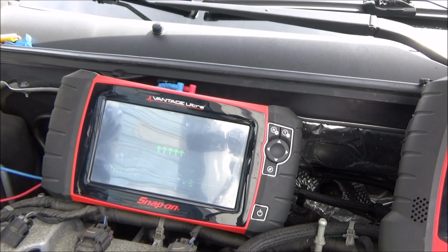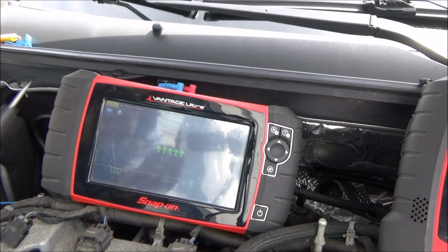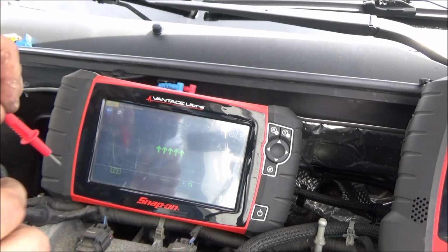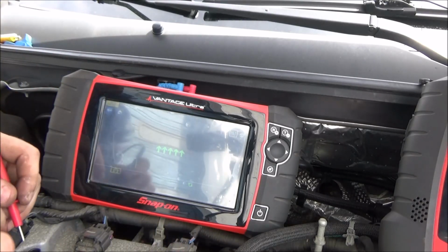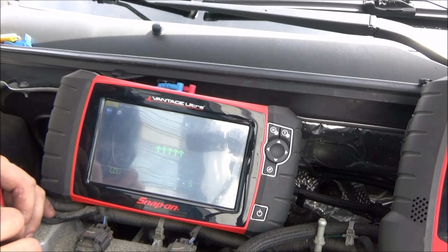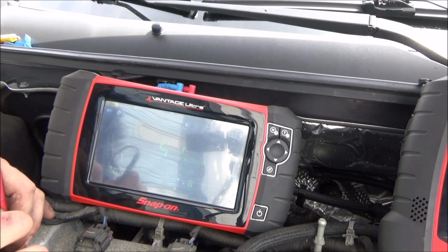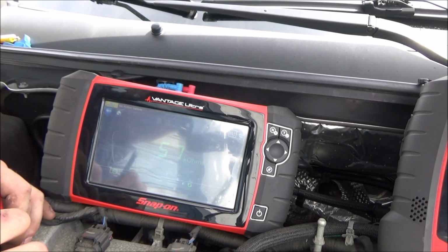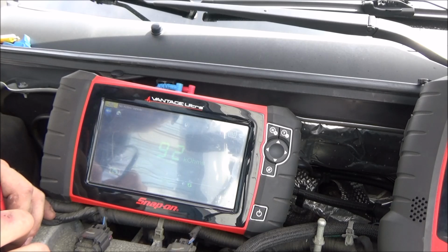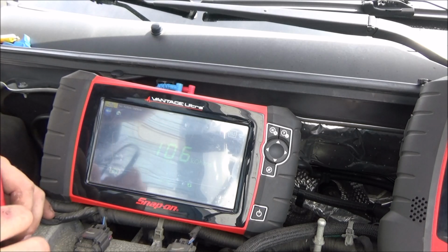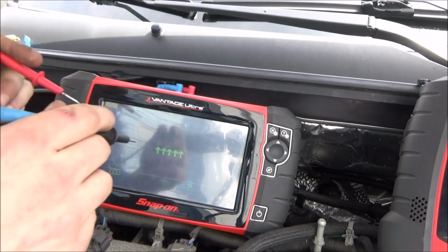All right, guys. So the resistance check on the solenoid. All I'm doing is taking a set of meter leads here, and I'm just going across the contacts of the solenoid itself. So I'm going to start with the intake camshaft solenoid. This is the one we had the trouble code for. I'm just going terminal to terminal, and I'm seeing what we have. So it looks like we have this number stabilized around 60,000 ohms. Guys, I can already tell you that's bad. It's going up to 100,000 as I'm flexing these pins. I mean, this is way out of spec, guys. As I've said before, 10 to 13 ohms is generally what I see on these.